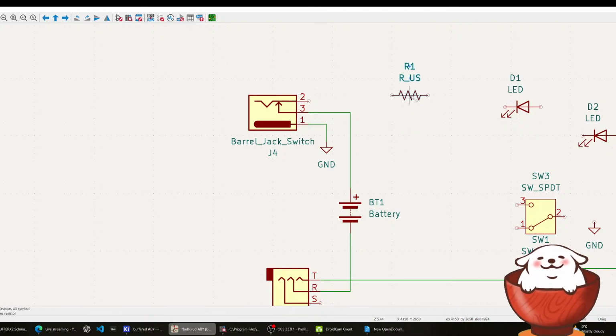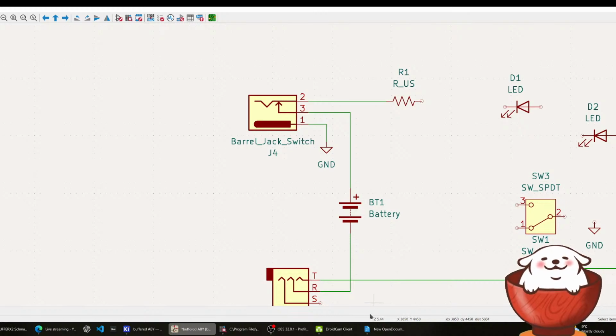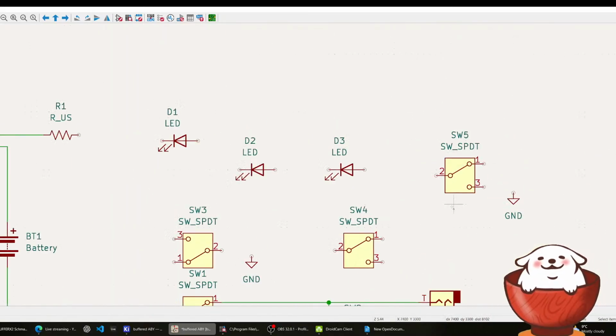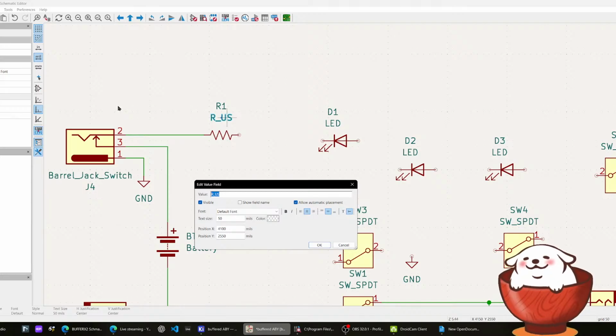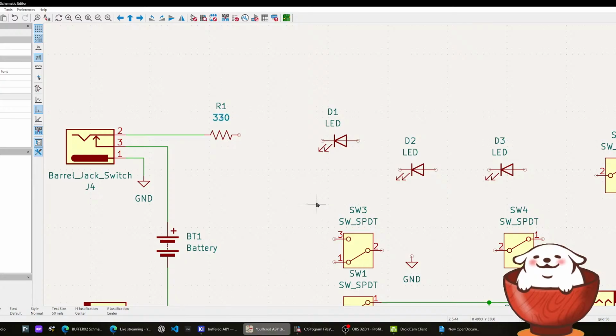And I'm gonna try to put a resistor right here, and we can go transistor. You can be in any kind of setting, which is I think I have at 330, but we might go a little bit more. Last time we did it at 330 ohms. Yeah, we can just do our 330. Okay, so we do R1 330 and LED.